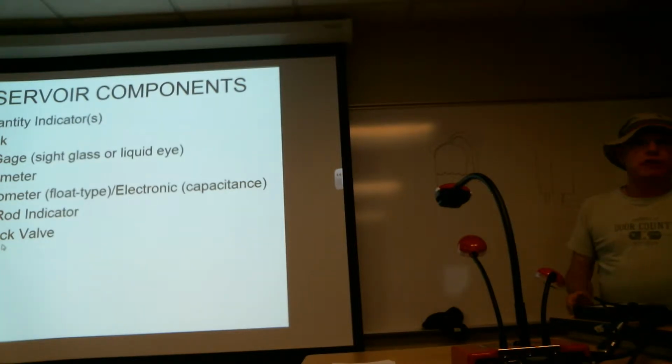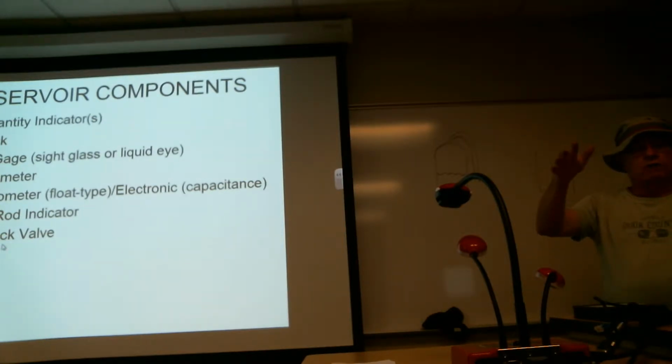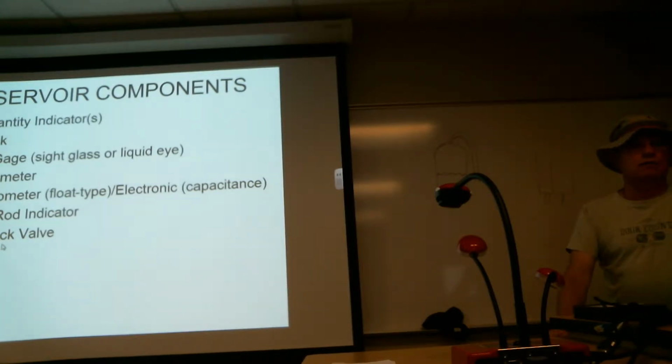They may have a check valve. And again, the check valve, if it's installed, works kind of like the vent caps that you find on batteries for aircraft. If the battery becomes tilted, the little lead weight falls to the side, and what that does is it checks the flow of electrolyte, preventing you from losing it from the battery cells.